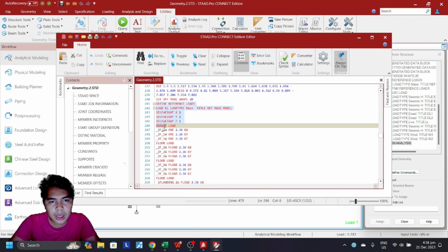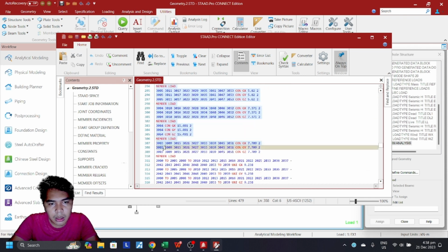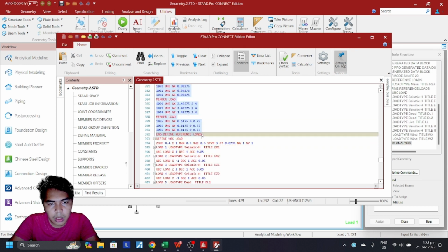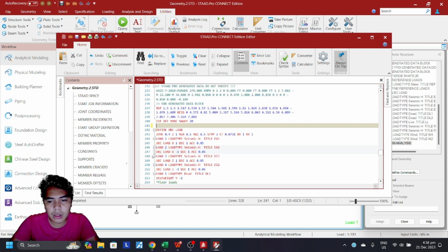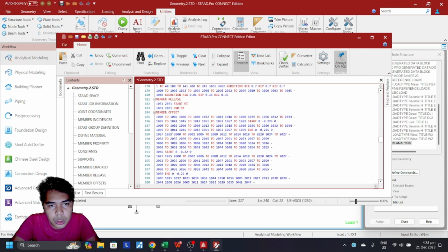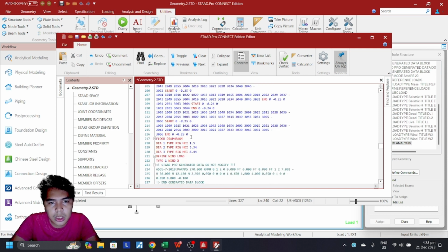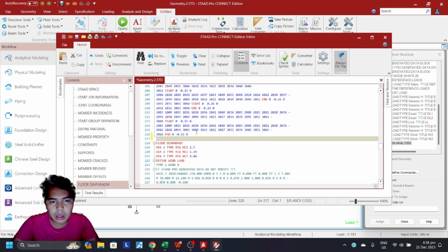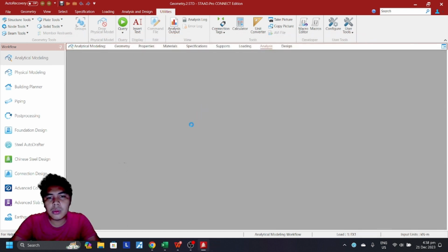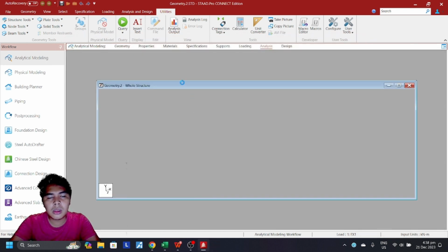We're going to highlight it, and until the end of reference loads, press Ctrl X and remove this extra space and put the reference loads just after member of set, which is here. Enter Ctrl V and save your work. Press X and let's wait for it.